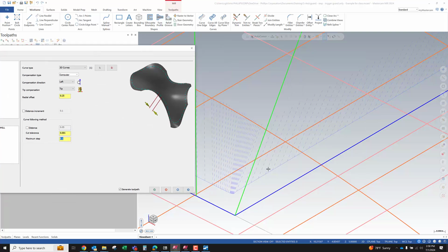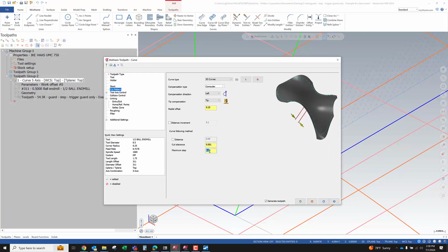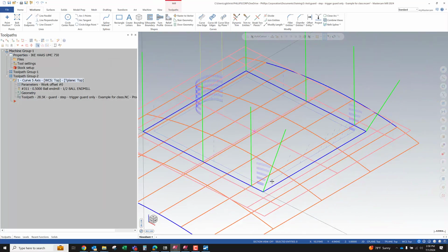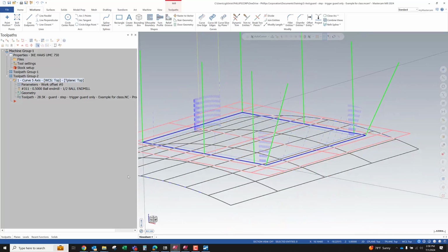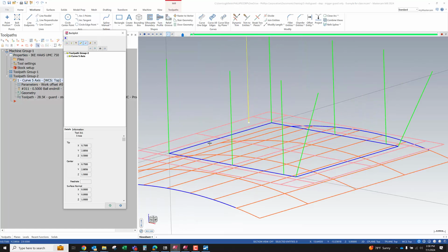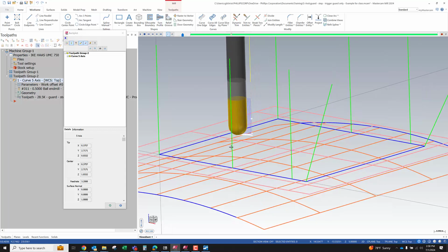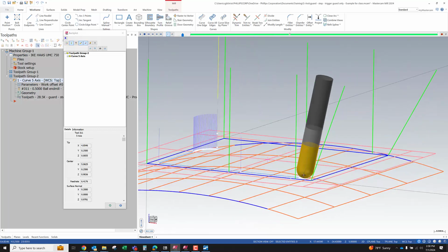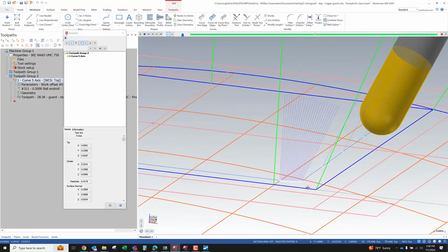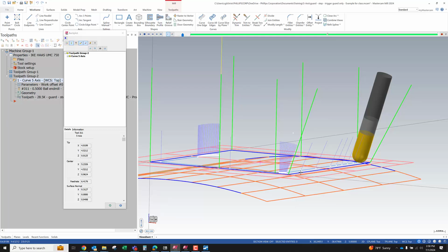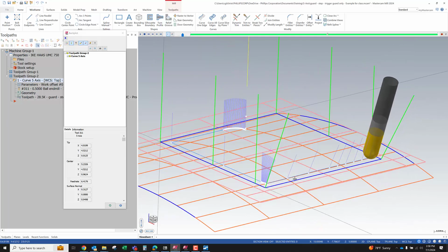So that's one of the things that's killing us here, right? We're getting a vector every 100 thousandths, whether we like it or not. So if I set the maximum step to like 3 inches, that should take care of quite a bit of our issues. Because now, if the vector hasn't changed, I'll output one every 3 inches just because. But if the vector doesn't change, I don't need to change it. But look what happens where the rotation is. So this is the best of both worlds.